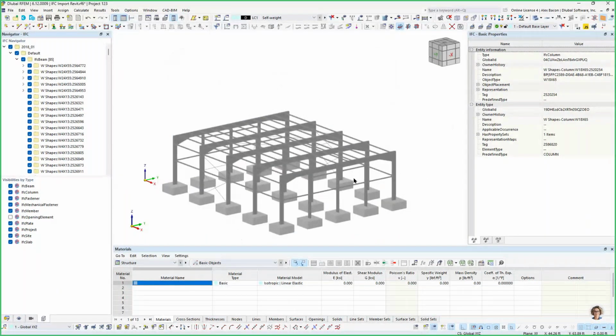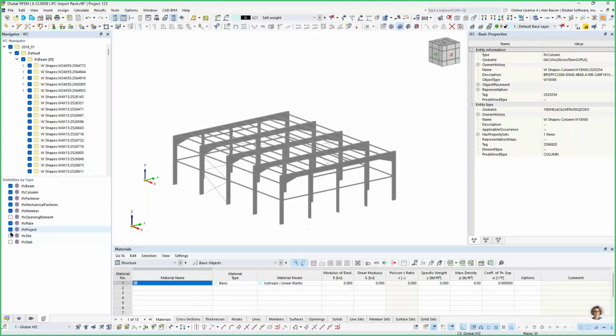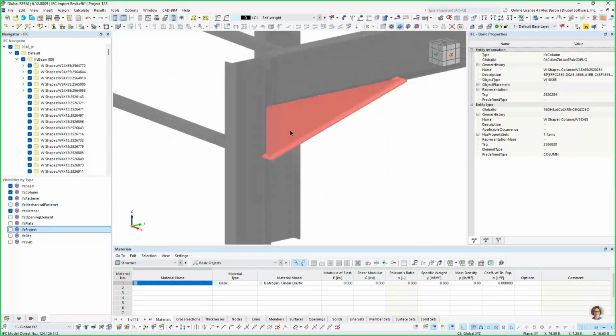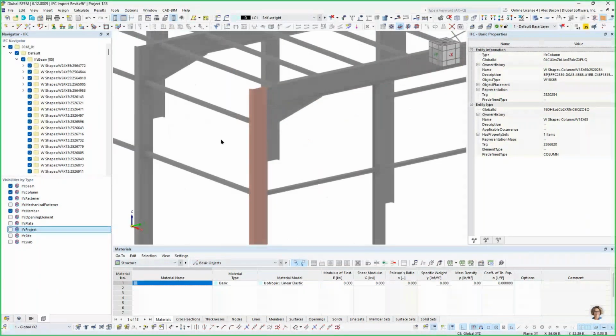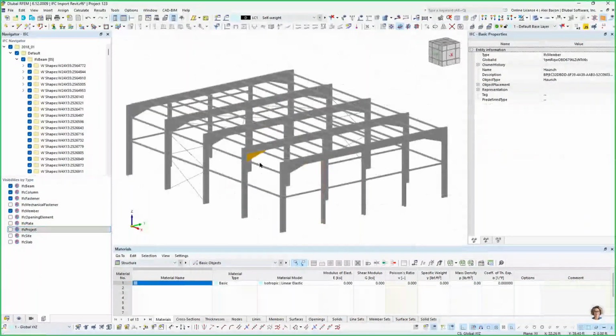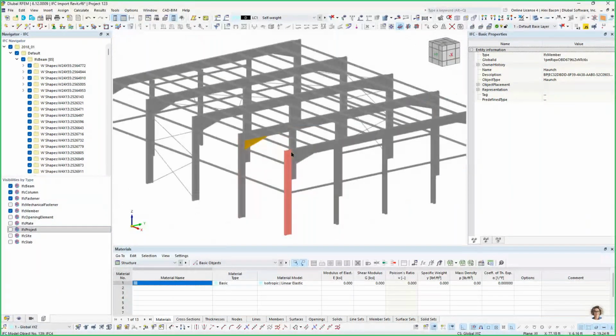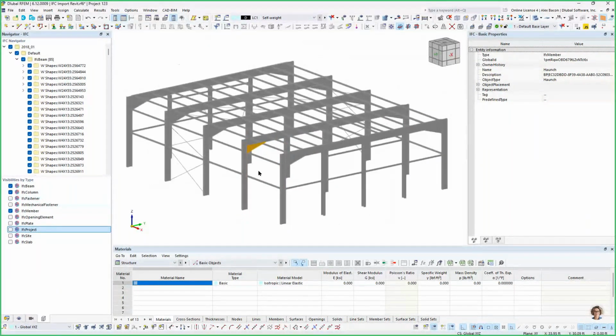And so now what I can do is I can just hide these IFC elements that I don't need anymore. We'll hide the connections and fasteners. You could convert these connections and fasteners, or probably mostly just the fasteners, into straight elements if you wanted to, but it's not really practical. So I'm going to hide all of them.